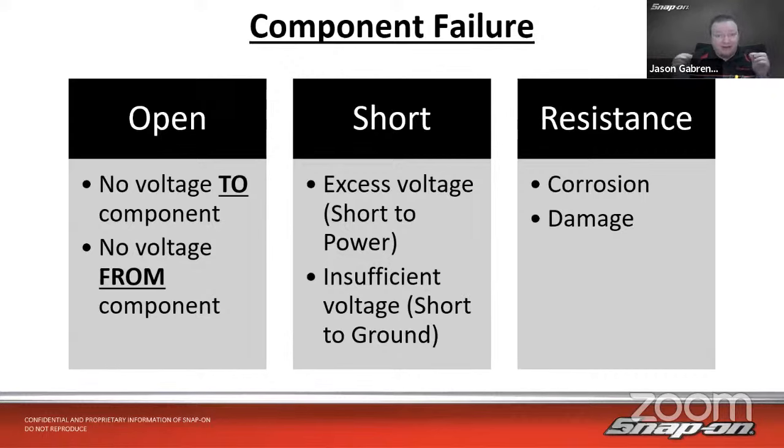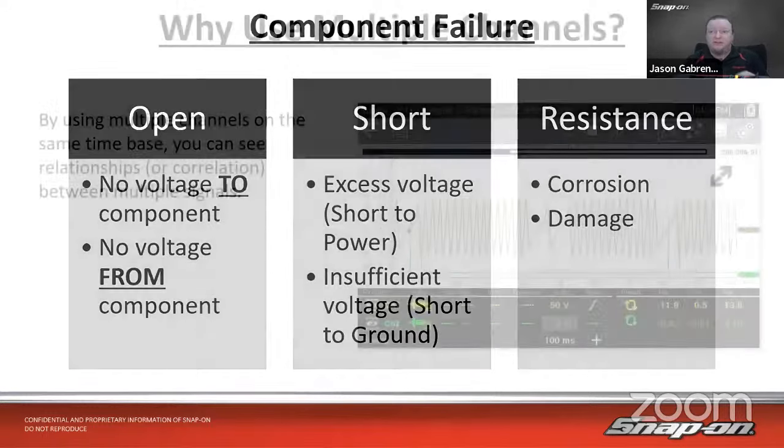But will that tiny little strand of copper wire start a car? It's not going to be able to carry the amperage. It's going to get really hot if it tries, but that's a resistance issue, and you're really not going to be able to tell it with an ohm meter. Really, you need to load the circuit ideally, so maybe a headlight or something like that, which a lot of folks use. But you might also be able to tell by doing a voltage drop and seeing where the voltage drops off in the circuit. So these are the ways we can test.